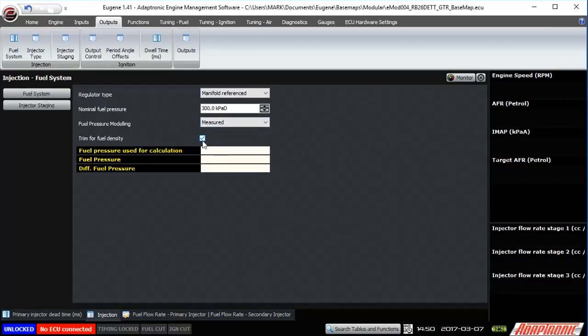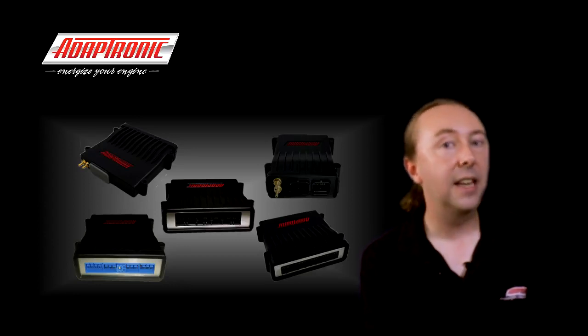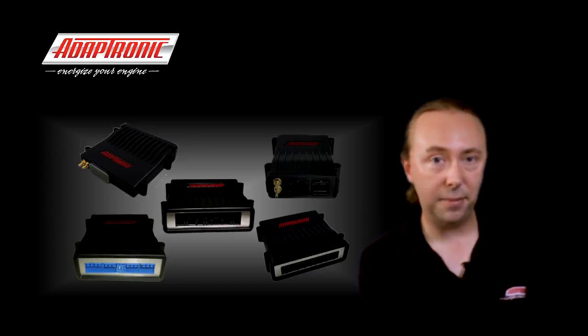The next checkbox is to trim for fuel density. The fuel density changes with temperature, and this change actually is different between petrol and E85. So the ECU has a built-in table to compensate for the change in density, and if you have this checkbox enabled, the ECU will look at the fuel temperature and make changes accordingly. If there's no fuel temperature sensor enabled, then the ECU uses a model for the fuel temperature which starts off at the engine temperature and then stabilises at a steady temperature after that.